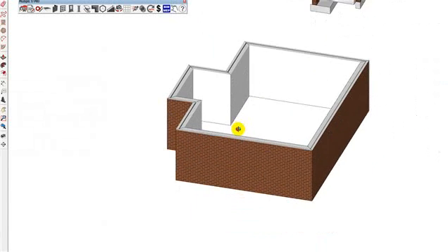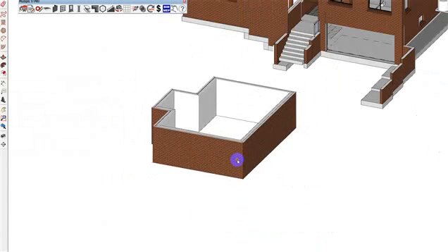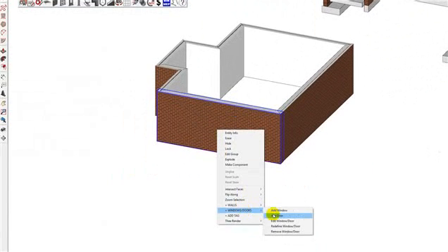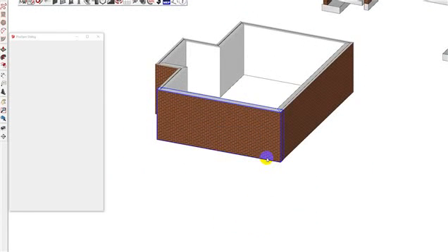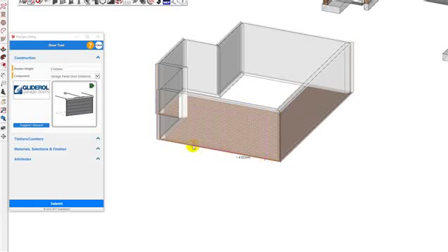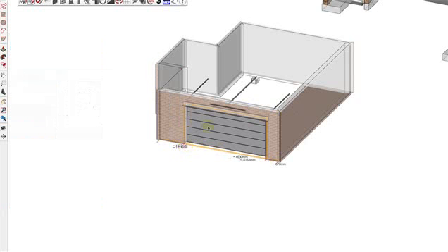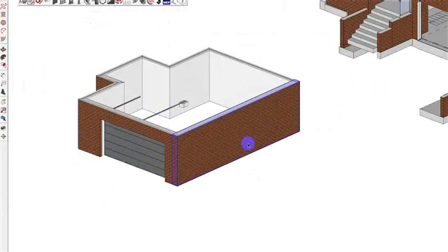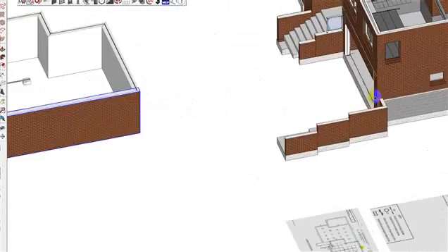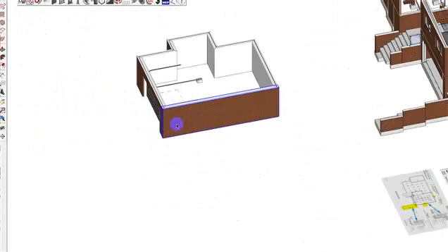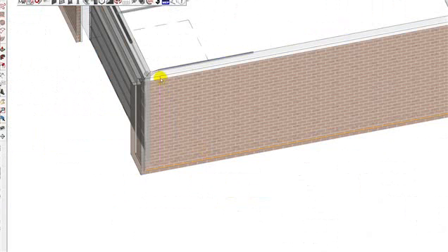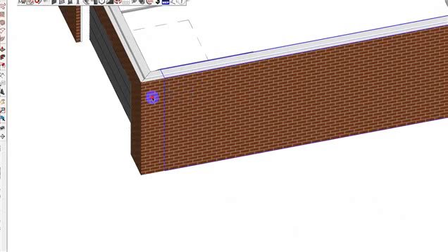Okay. So now I have a brick veneer wall, but on a couple of the walls, number one, you had your door here, add door, and it goes all the way down to the floor, as you can see. Right, so I've got the door there, automatically put the steel beam in, so that's all one. Now over here, you've got a retaining wall coming back about this distance. So what I'm going to do is split the walls, split wall here, like that, and go enter. Right, now I have two walls, you see.